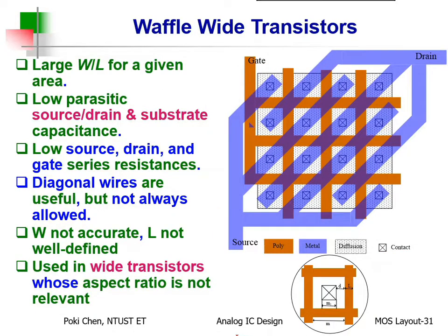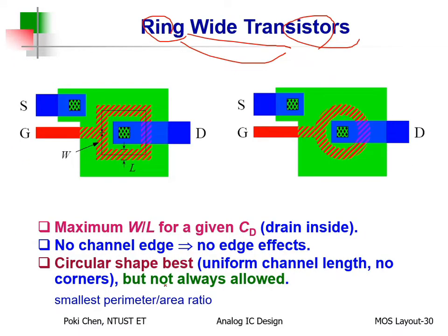Anyhow, what is the idea here? Actually, for each internal layout, the idea is quite similar to this. And what is the most important idea? You can see, look at me. I told you for the stack layout, source and drain. Then you flip it, source and drain. Then both sources can be stacked, overlapped, to reduce the area and the parasitics, roughly speaking, by 50%.